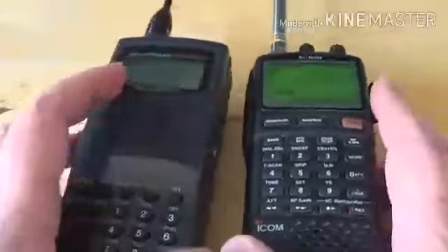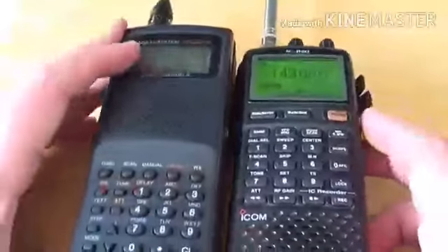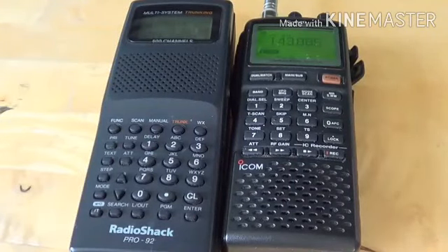So hopefully that gave you an idea on how the squelch works and why you have it on the radio. And of course, why would you like to turn off the squelch? If you're dealing with extremely weak signals, then you might want to take it off, because some very weak signal just barely above the noise floor might not be strong enough to actually be heard if you put the squelch on.